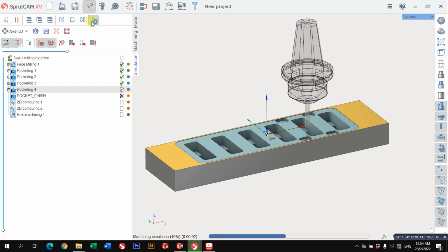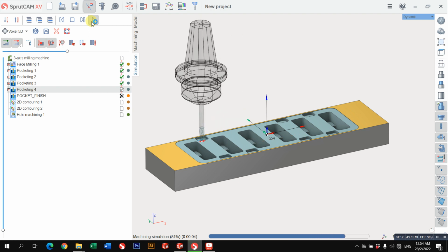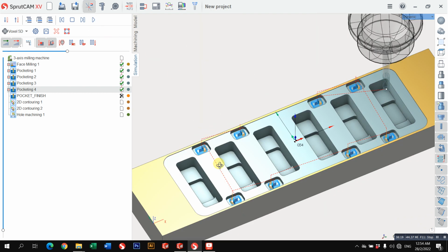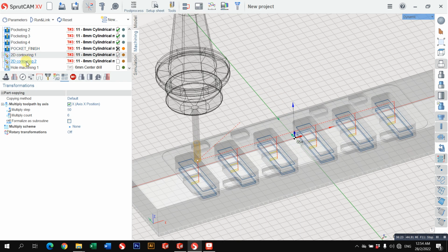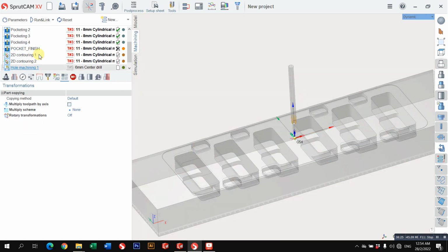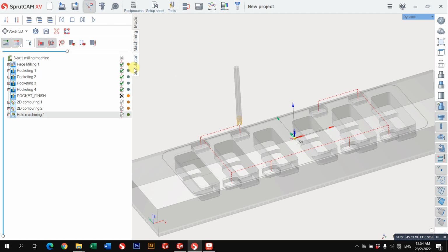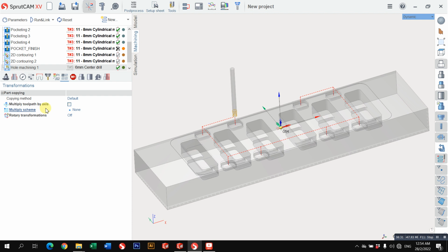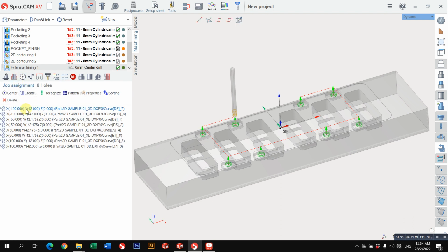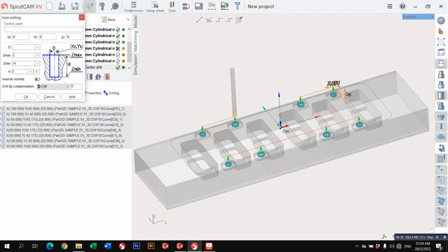Okay, continue our drilling process. Copy and paste. Now it's a pack drilling. And change our tool to normal drill. This also 6 mm drill. This one have a working length of 155. Okay. Speed. Same hole but different depth.